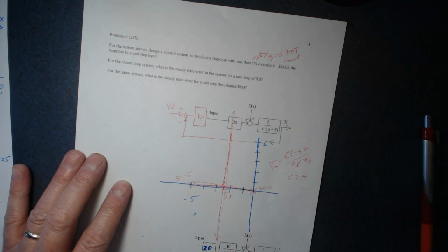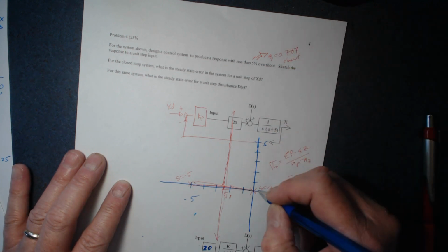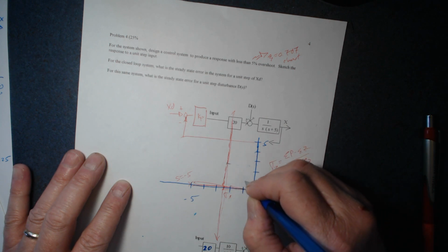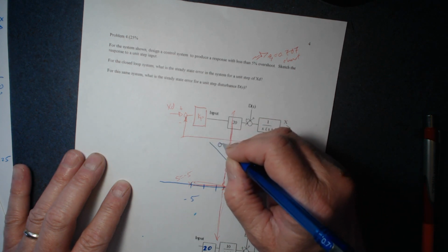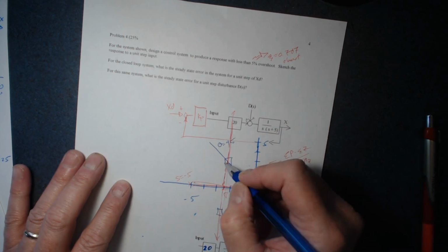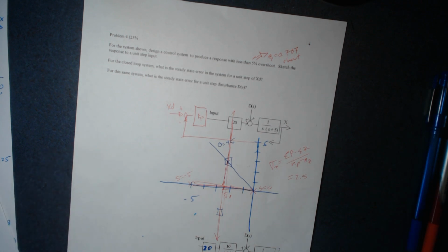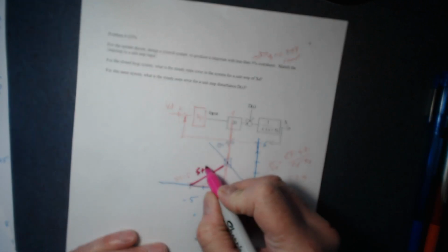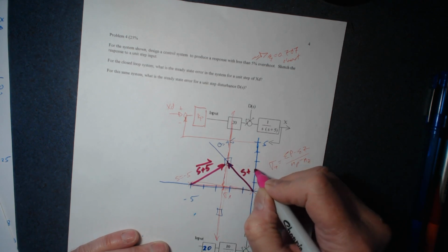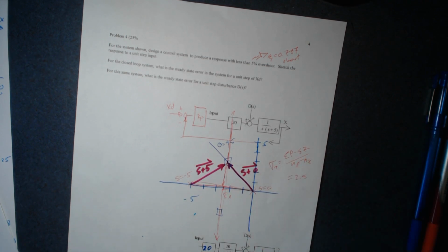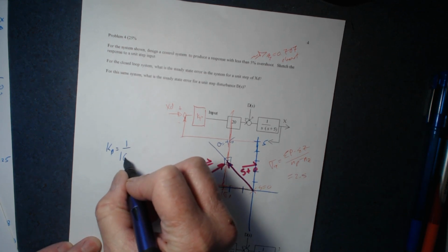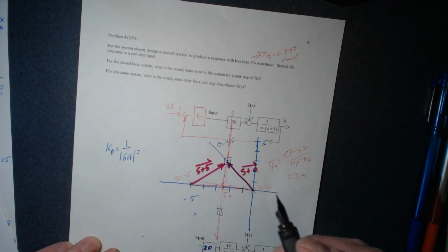And then I'm going to say, oh, you know, zeta equals 0.707. This is going to be 2.5. Okay, so here's a 45-degree line. 45. These are my desired root locations. So for this root, I would like to draw this is going to be s plus 5, s plus 0. And all I have to do now is find out that Kp is equal to 1 over magnitude of GH, which is equal to,